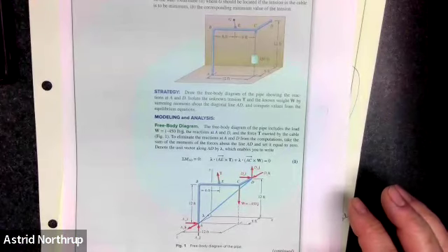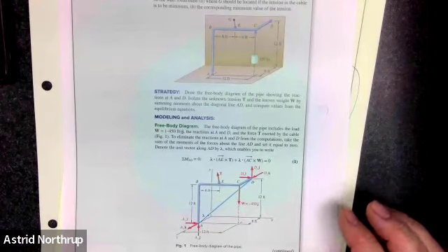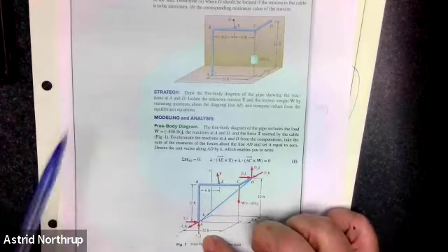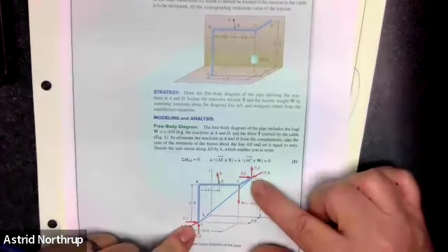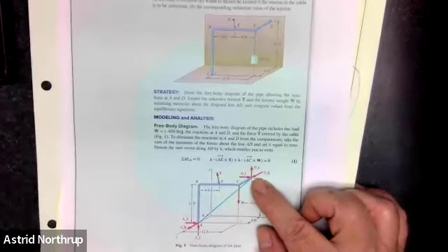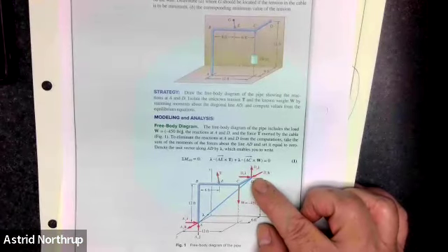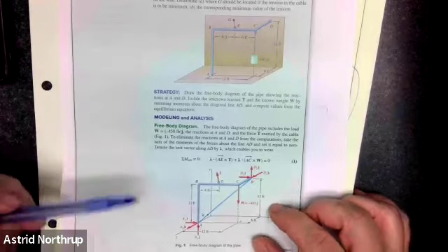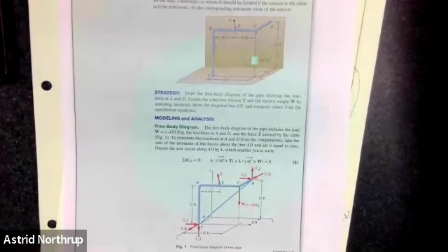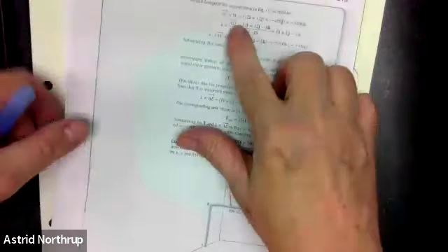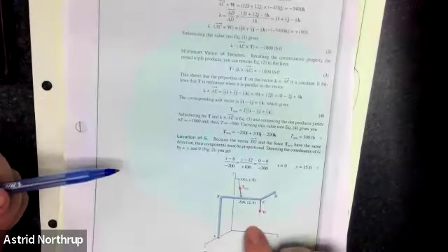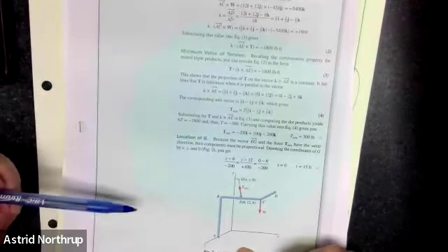We cannot solve for 9 unknowns with 6 equations. So they'll give you some information in here, but basically you can't really do anything with reactive forces. You just have to leave them as those unknowns unless they give you a number. Sometimes they'll say the Y component of the reaction at A is some number, but if they don't, you just have to leave them as variables. Then you break them down into unit vectors, forces, all of this is the way that you've worked it before.